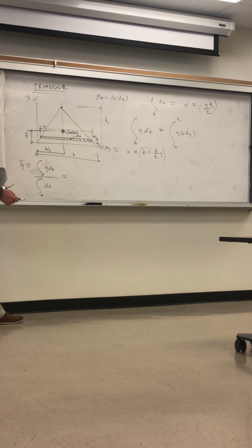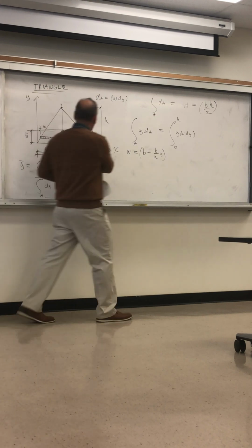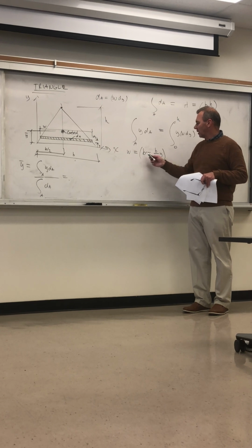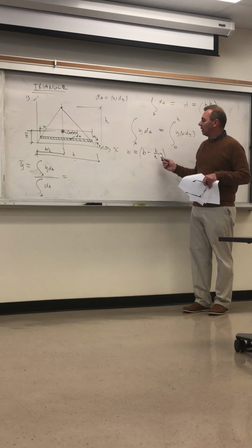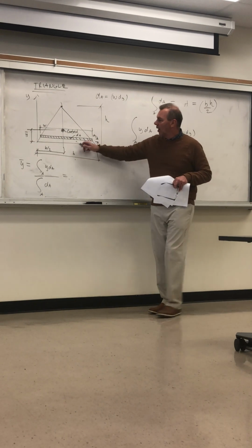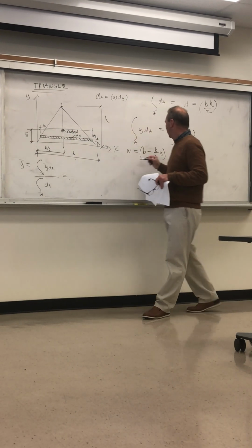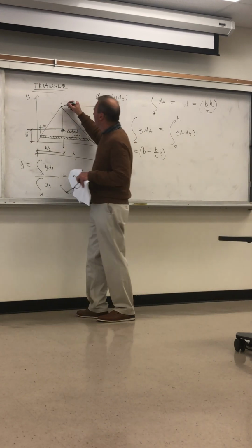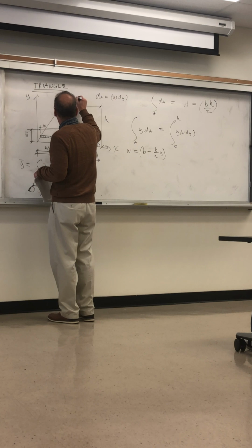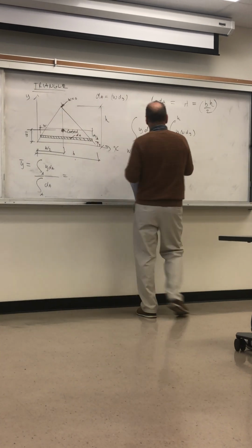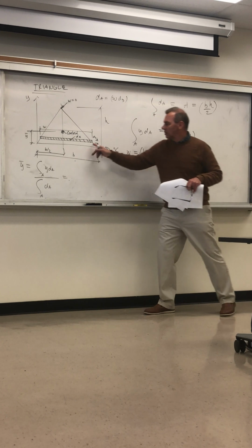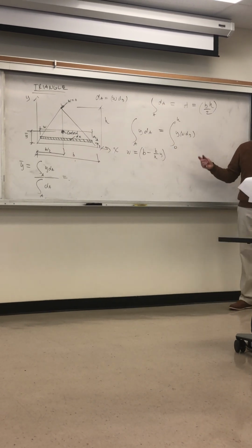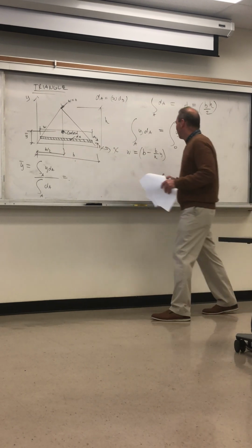So in other words, when y is 0, this is b, the width, and then as y increases, this decreases, and finally, when the y position going up becomes h, that cancels, and you have b minus b, which is, at this point, w is 0. When y is 0, this cancels, and you get back b, which is the width at the bottom of the triangle. So this is the correct width as a function of the position.